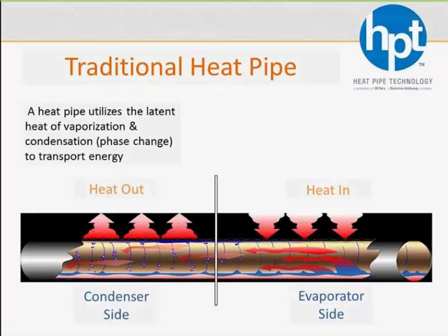So this screen may be very common to everybody, but this is your basic heat pipe, a single tube, what we call a single tube circuit. If you've seen the swivel sticks that dip into the cup of hot water and get hot really fast, that's exactly what this is. Basically, you got a tube, you got refrigerant inside. As soon as you apply heat to one end, the refrigerant on that end is going to pick up that heat and boil.